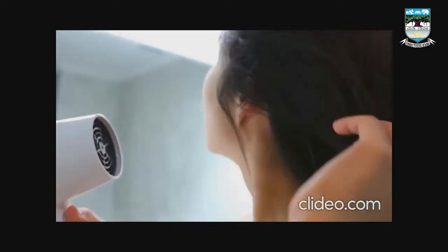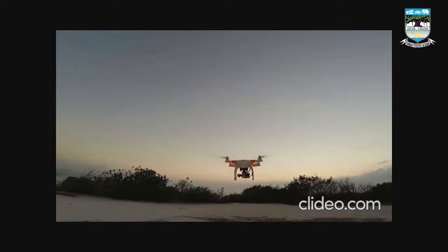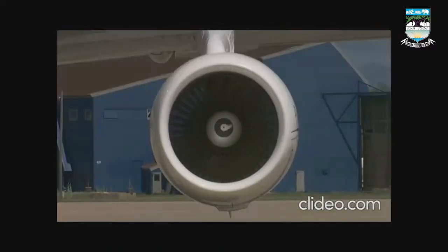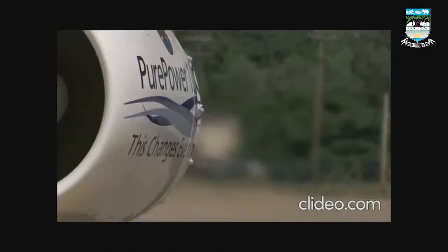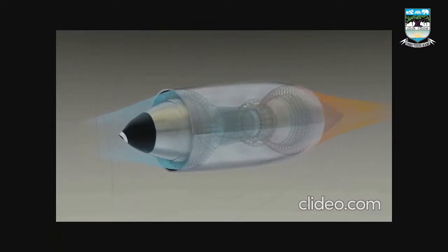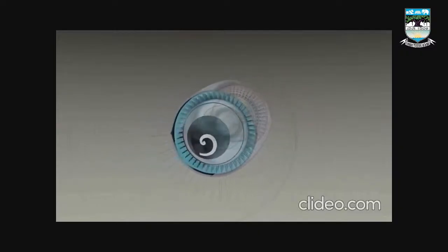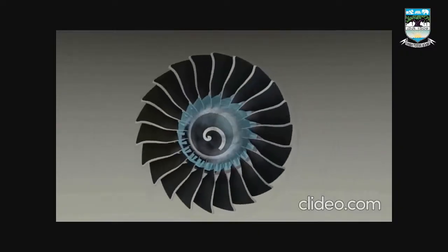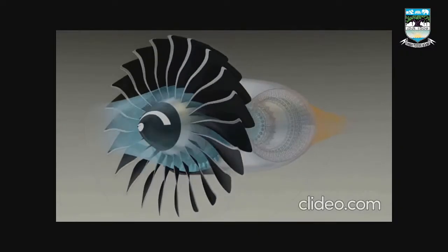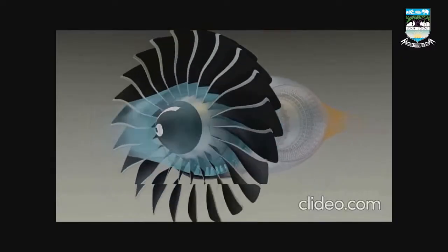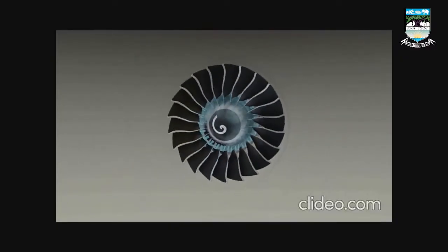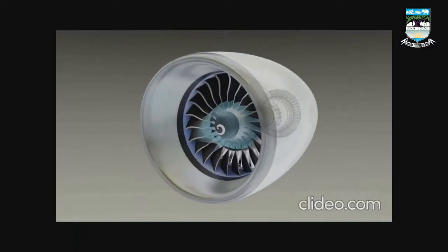A rotating disk is a commonly encountered component in aero engines, automobiles, turbines, pumps, compressors, flywheels, and in a number of other dynamic applications. Many of these applications are exposed to elevated temperatures where creep deformations become important. The enhanced creep of lightweight aluminium and its alloys may not permit their application at elevated temperature. From this point of view, any research work on composites should attempt to analyze creep in structural components like rotating disks made of lightweight aluminium ceramic composites, so as to develop more reliable design codes for real-life applications.